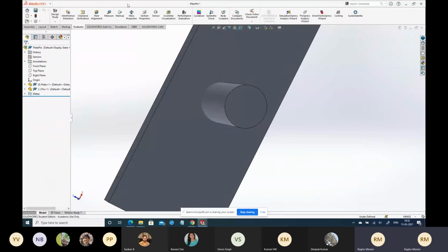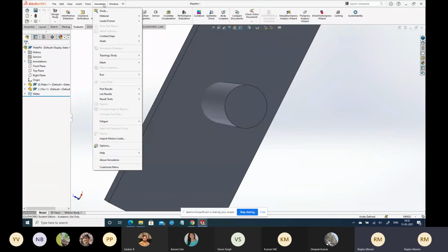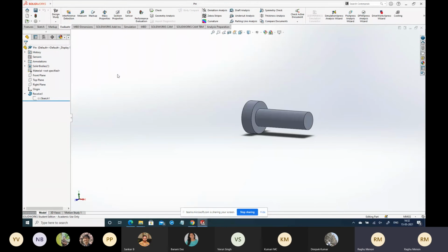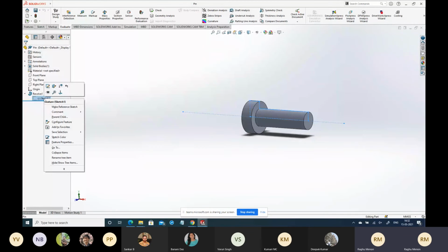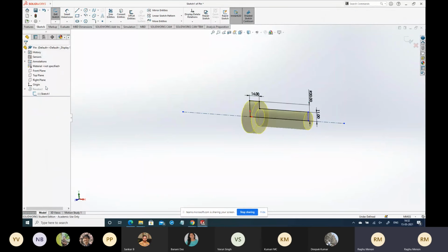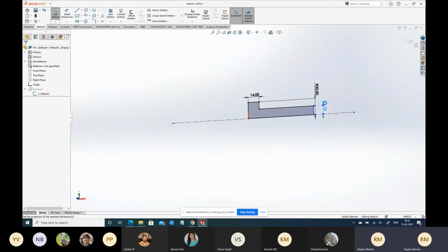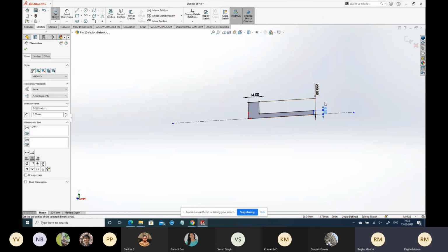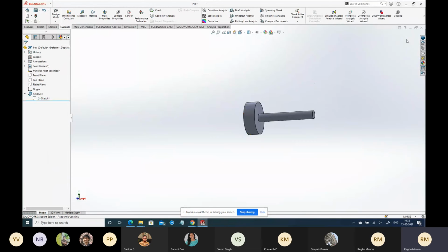So now to change that, you can go to the other part, which is basically window, and go to the pin part. You can also make it such that every time the hole diameter changes, the pin dimension also changes. That needs a little more thorough modeling if you wanted to do that, but I'm just doing this as an example. Since the diameter is 10, you need to keep the radius as 5, right? So this looks funny in terms of proportion, but that's what it is.